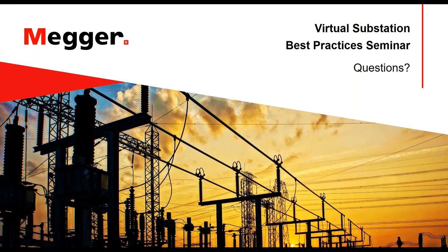Now, we know that it doesn't have a probe. It is not reading directly the temperature of the actual conductor, but that is the closest we have in the field. Now, in some power transformers, especially large power transformers, you will actually have an optic fiber probe that will actually give you an accurate reading.